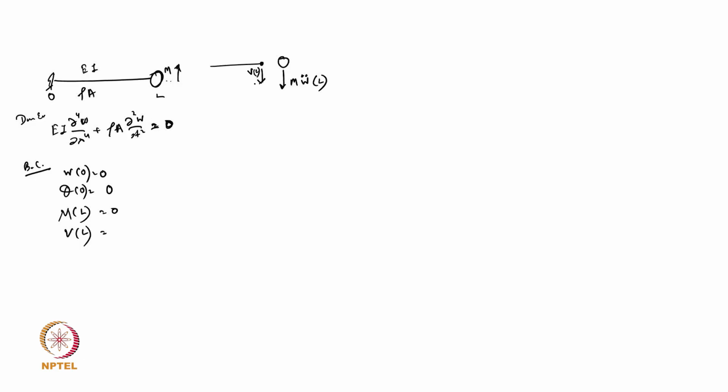So if I think that is a cut, because always once we are doing the shear force or bending moment, we can get it from the cut. If we do not cut, we will not get bending moment, we will not get shear force, because they are the internal reactions. So we have to cut it there. Once we cut it there, this will go here, this will go up, VL. Now we can balance that. Agreed? So if we balance this one here, you can say VL will be equal to M W double dot. Agreed, all of you?